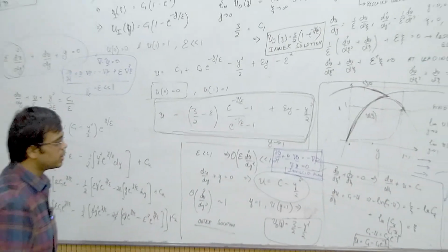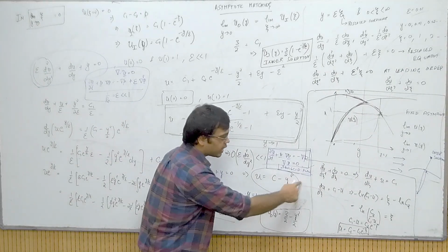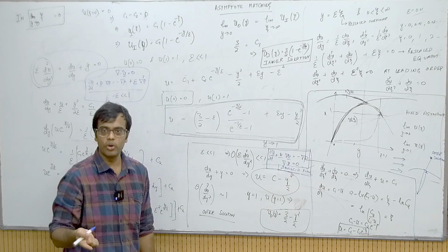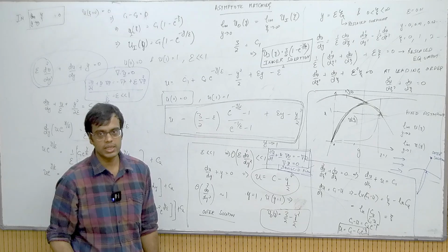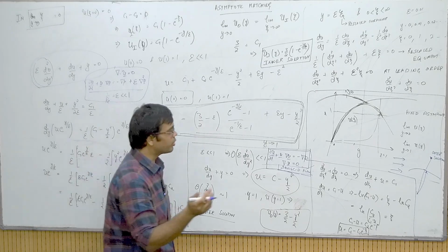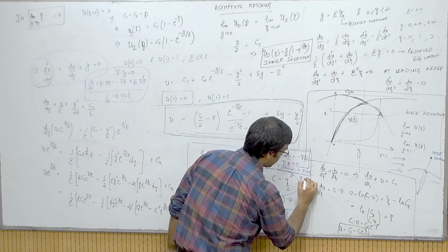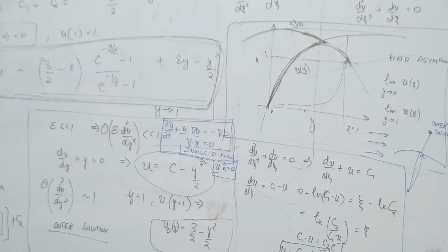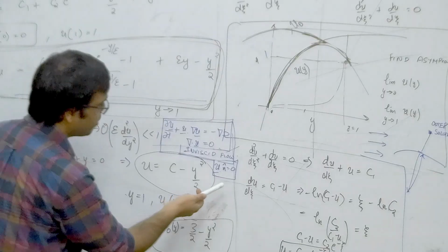No slip. So inviscid flows cannot obey no slip boundary conditions, and you will solve the flow without any no slip boundary condition. If you have a surface, all you can say is that u dot n is 0, assuming it is a hard wall of course. If it was a porous wall or something else then you would take a different boundary condition.